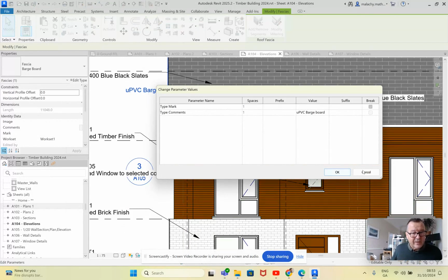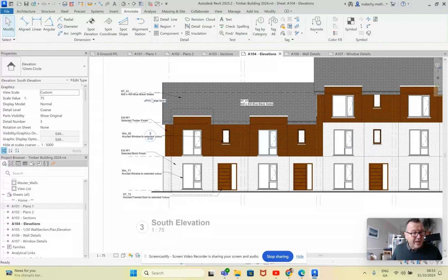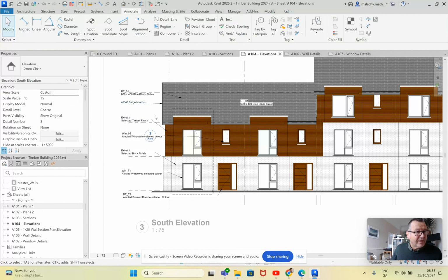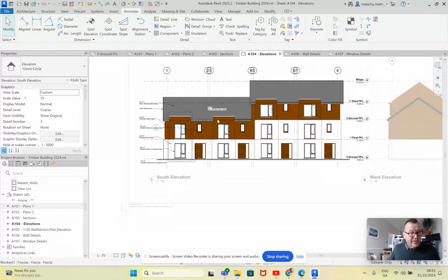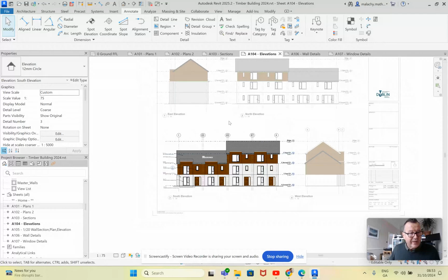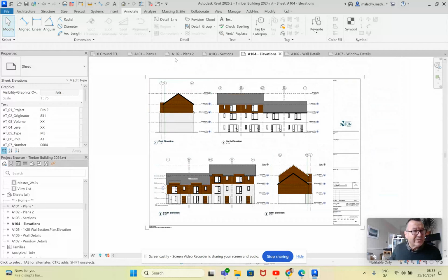That's what I'm talking about there. All right, so you'll move that into position. Escape. Select, move it, and put a leader with that, something like so. All right. So you can populate, and a lot of these will be repetitive, obviously, because there's quite similar finishes used throughout the building there as well. Right click, deactivate the view, make sure that's filled out there. That sheet is good and ready to go.